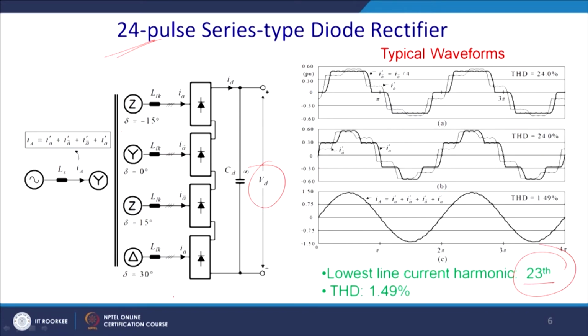You see there is one part of it, this part and this part is nothing but your 12 pulse converter. So, you can have a star with a 0 phase shift, and thereafter with respect to it a 30-degree phase shift. There is a vector group that will operate, it is YD11.